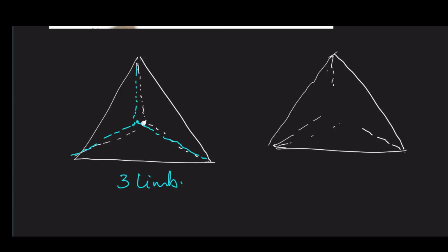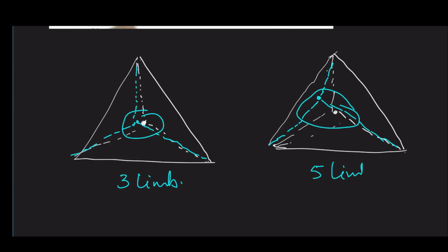So what I am trying to say is, if this is the centroid, then in case of a 5-limb, your new neutral may come anywhere like this. If you measure the corresponding shift of neutral for 3-limb and for 5-limb, you will see that in case of 5-limb, neutral perturbation is quite high compared to 3-limb. The same kind of thing happens in case of shell type transformer.